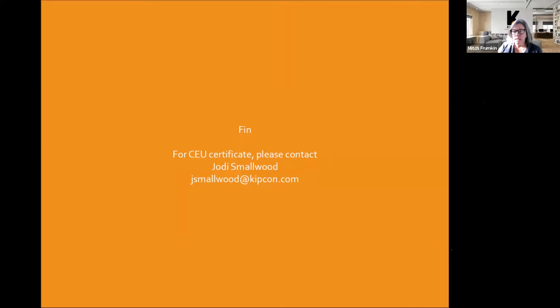it only provides protection if you do it early and you do it regularly. So we recommend, if you're going to do it, that you apply the first seal coat 2 years after pavement is installed, and then you regularly re-seal coat it every 5 years thereafter. So you have to do it early, and you have to be consistent with it.